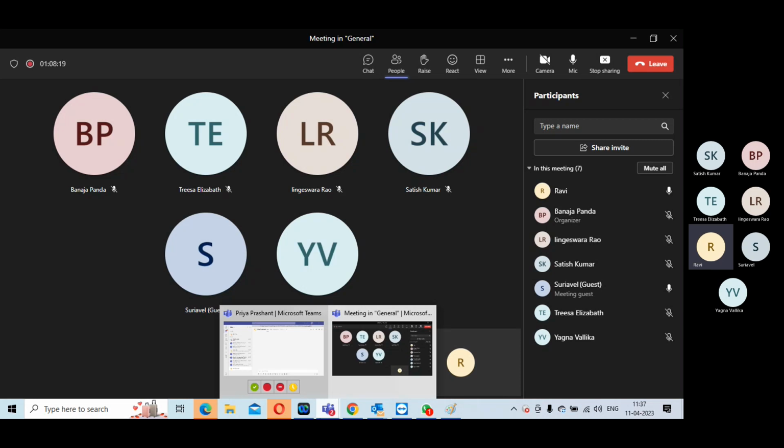Why CTS criteria? After CTS, you will figure out that the clock cells are getting split and your clock skew is more or your insertion delay is getting longish because some logic is placed somewhere far off, which is creating your longest insertion delay or you are unable to balance.